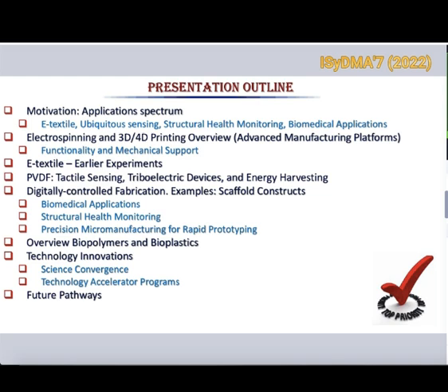To hold these fixtures in place, obviously we want to have integration of these two processes, as I have mentioned. In the following slide, what I have shown is essentially the use of electrospinning. We have been working on pressure sensing membranes, that is, how different combinations of polymers and bio-based polymers can serve as pressure sensing membranes. In addition, we have incorporated PVDF, which I'll explain a little later, for energy harvesting applications, so that we have sensors that are pretty much